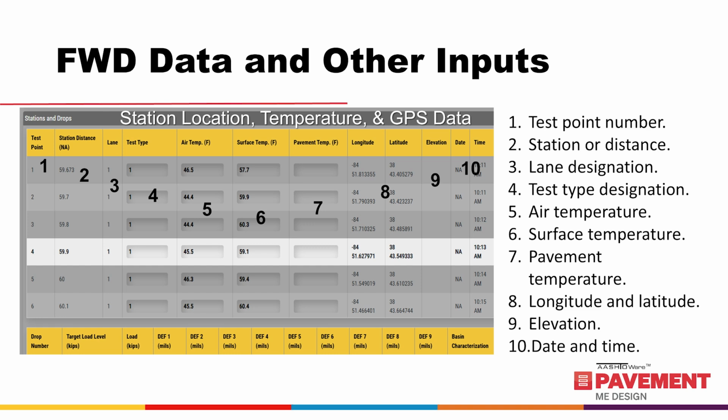For area testing like parking lots or other similar facilities, this can designate the longitudinal distance and lateral offset. The lane designation can identify the direction, lane number, turning lanes, and other types of physical information. The test type designation is to identify the type of test like mid-slab readings, edge or corner readings, joint readings like for load transfer efficiency for PCC pavements and center lane or wheel path or cracked versus uncracked areas, and readings across transverse cracks for load transfer efficiency of flexible and semi-rigid pavements.